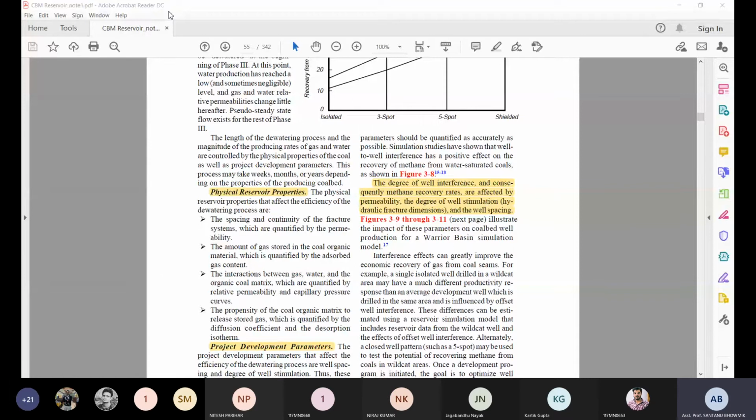If there are microcracks, first the microcracks will try to close, and if there are open cracks, obviously those will also try to close. So in a nutshell, the permeability is going to be reduced. Now, if earlier there was some water or fluid present in the open channels, at that reservoir pressure that water or fluid will also have some pressure, so you cannot remove that water or fluid from there.